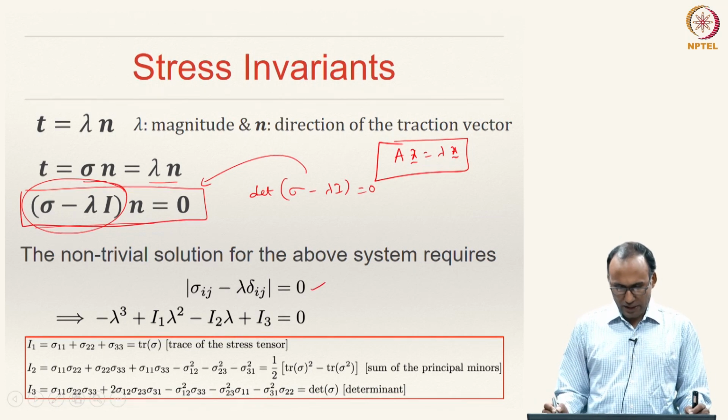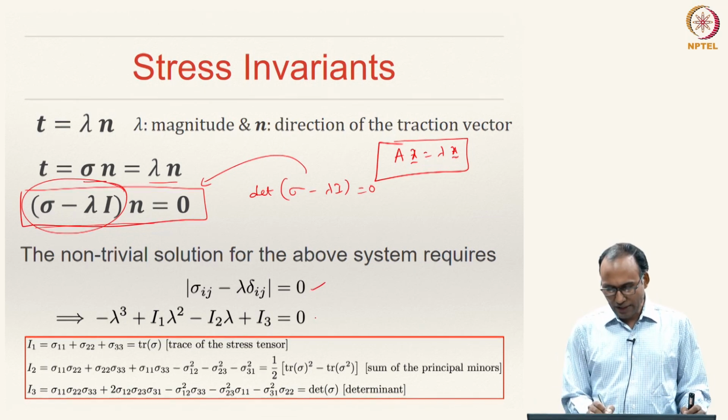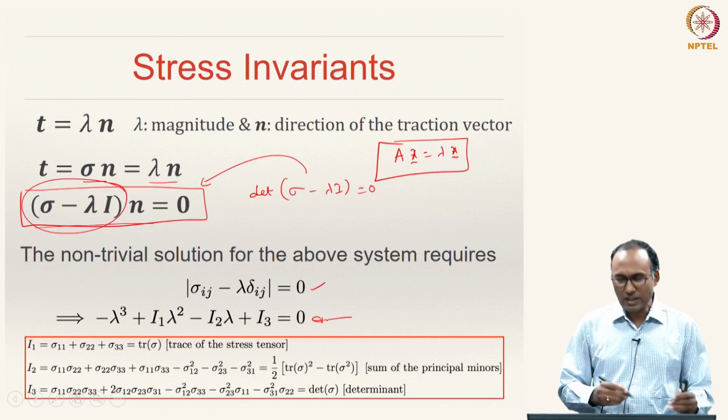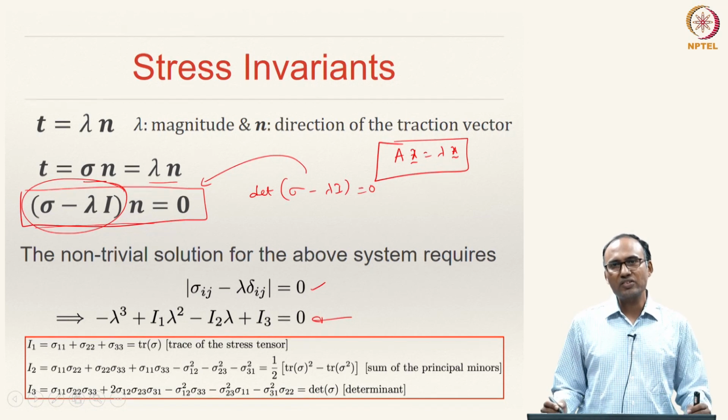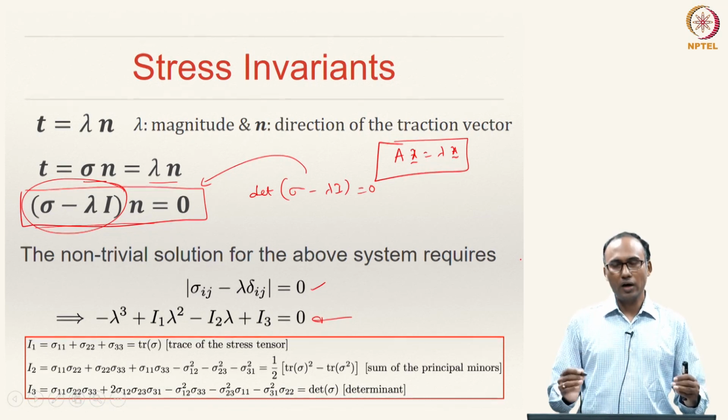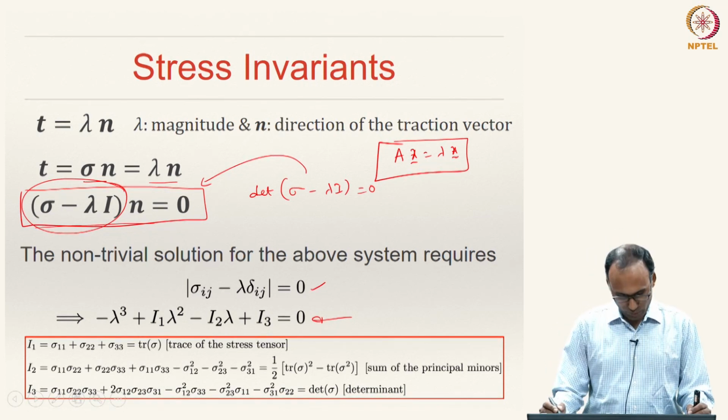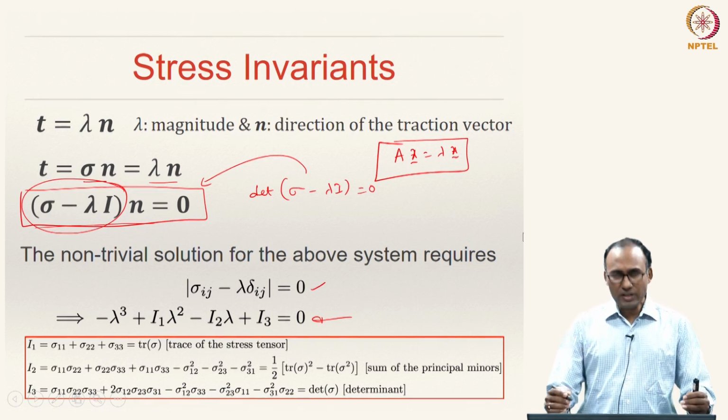That is what we have written here, and then we write the characteristic equation. The roots of this characteristic equation are the eigenvalues of the system, and they in turn represent the principal stresses of the stress tensor that we are looking at. And we introduce